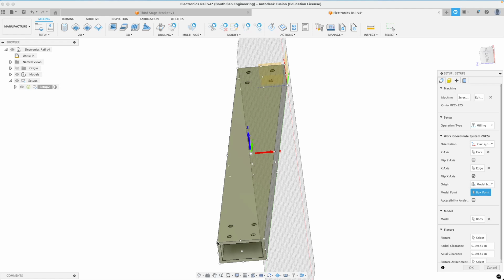I have bottom, middle, and top. I want to be on the top face of it. That's going to be my 0. So the 0 is always the bottom left corner of the work on the top of the workpiece. And now I have my origin set.